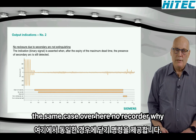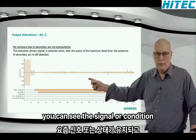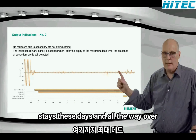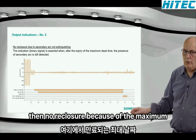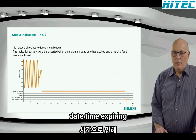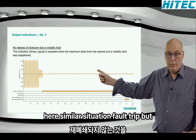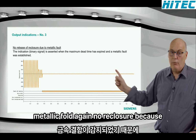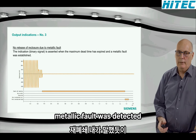The second case over here, no reclosure. Why? Because the secondary arc doesn't go away. You can see the secondary arc condition stays, and all the way over here, the maximum dead time expires, and then no reclosure because of the maximum dead time expiry. Here, similar situation, fault, trip, but now the voltage is very small. It's a metallic fault again, no reclosure because metallic fault was detected.